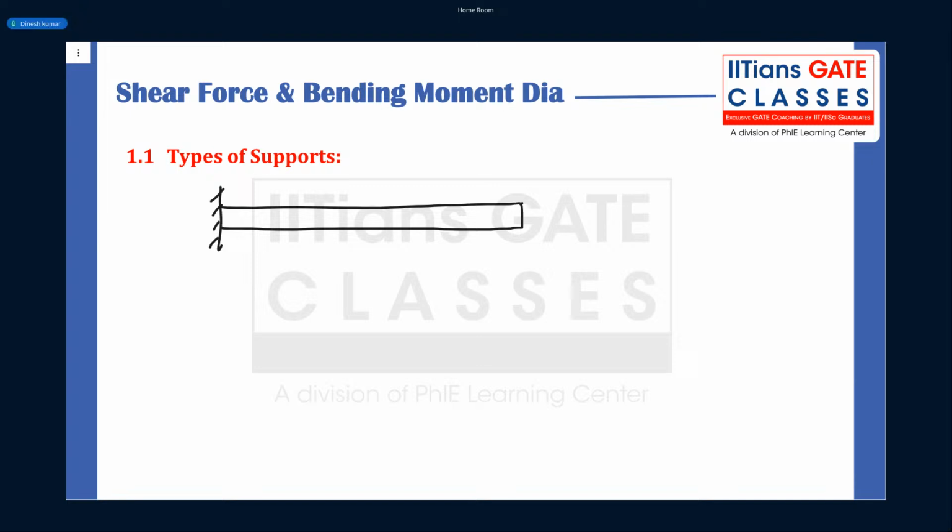Vishal, it can have an inclined load also. See, if you apply an inclined load, you will have two components: one is the axial component, and one is the transverse component. So it has an axial effect, axial stress, as well as bending stress. Clear? So it is a combined load. Now I am talking about a column. When a structure is known as a column, who told you it is vertical?